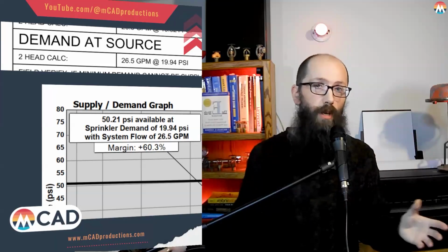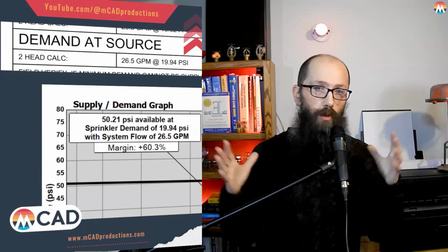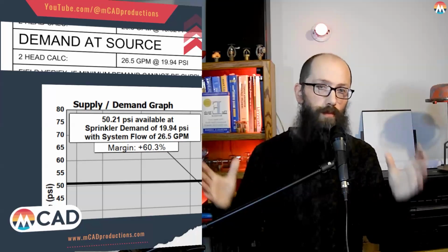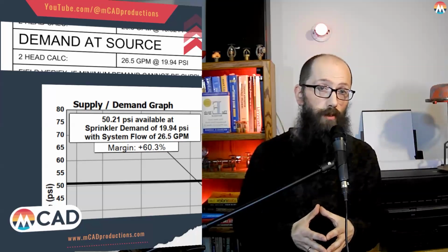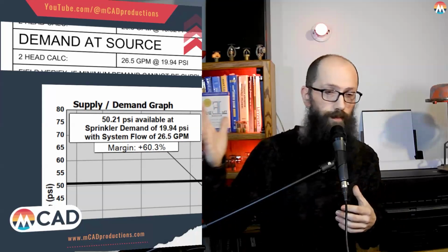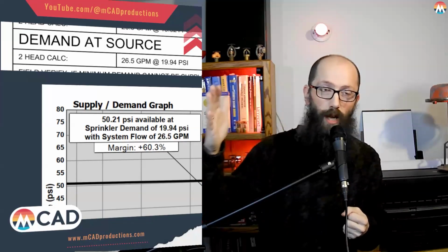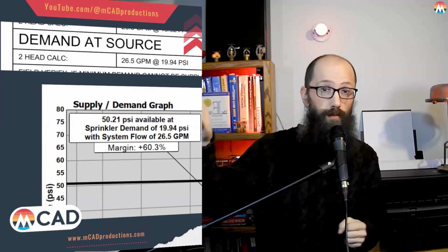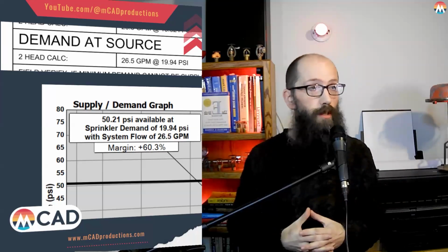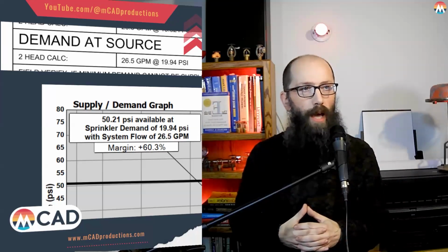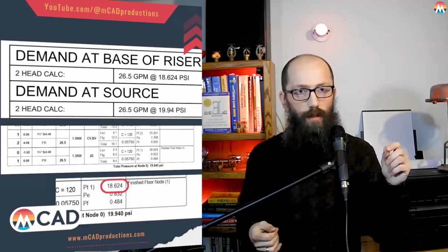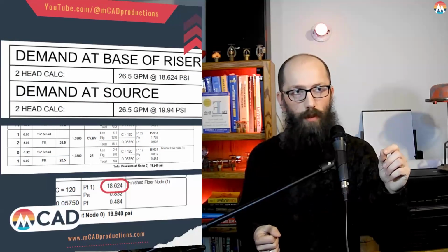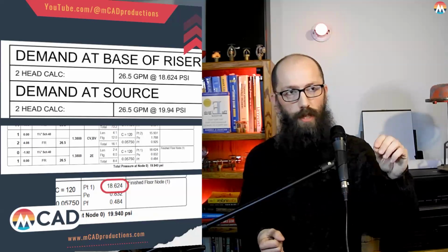And in the fire sprinkler world, everyone always wants to know the pressure required at the base of the riser. That's because it's posted on the riser itself, and when they do testing every year, they make sure that it's still available. To get that, we use the same GPM that we had before, but now we use this PSI.